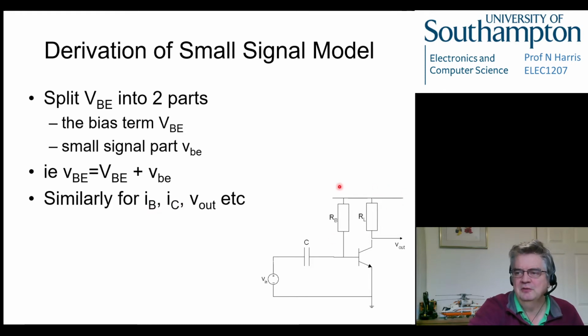And you can see that if we wire it up like this, then we've got a static solution here because there are no components that worry about frequency here. So as long as we have a power supply here, we will always get a current going down here. And if we get a current going down here, if it's DC, the only place it can go is into the transistor. It can't go through the capacitor because a capacitor looks like an open circuit to DC. It's just two parallel plates if you think about it, and there's no way a DC current can get through a parallel plate. Not unless the voltage gets super huge, of course.